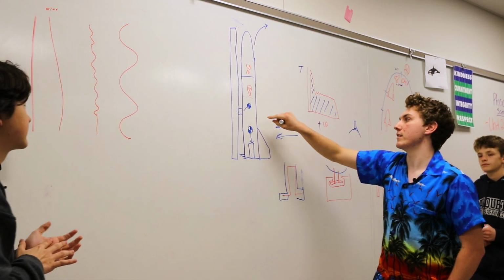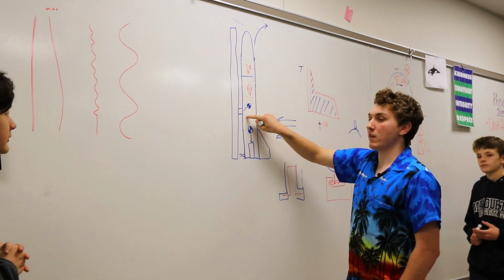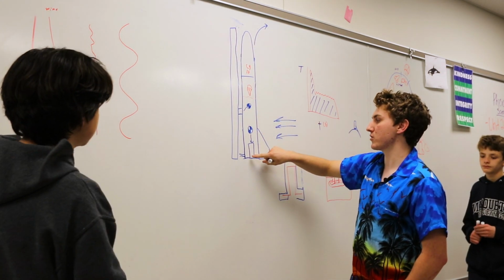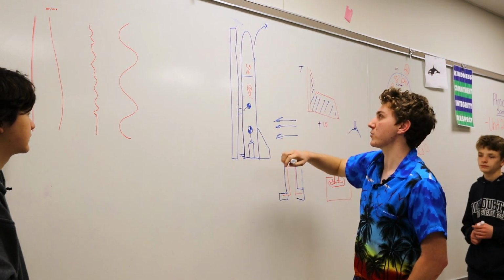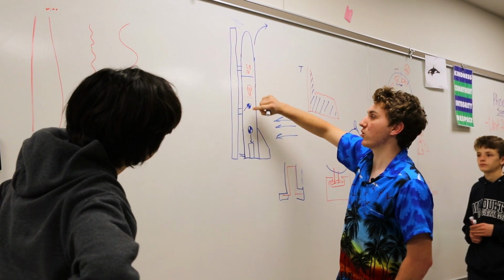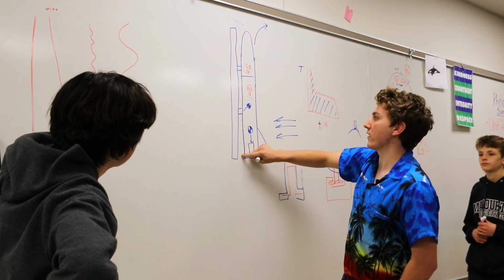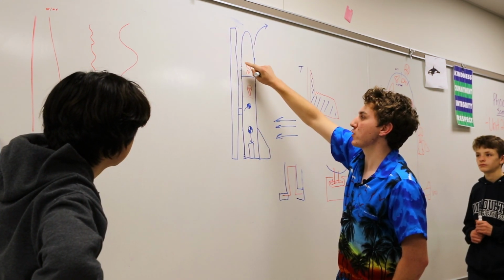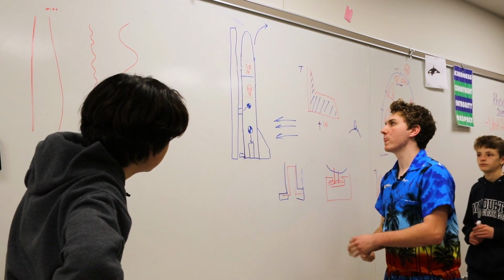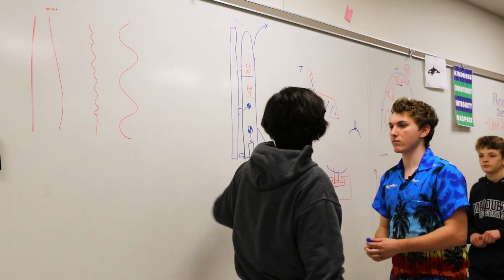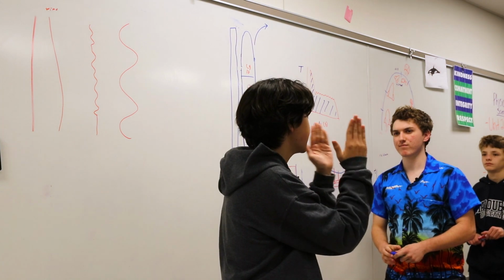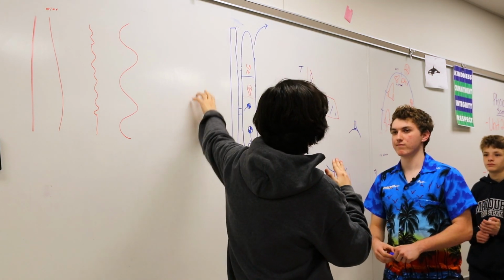The reason you do that is you want one aligned with center of mass so it's strong, and then you want one as low as possible so it's on the rail as long as possible. If there's only one rail button, it doesn't do anything. So you need two. It gives you two points of contact across the fuselage, and that keeps it angled upwards precisely with the rail.